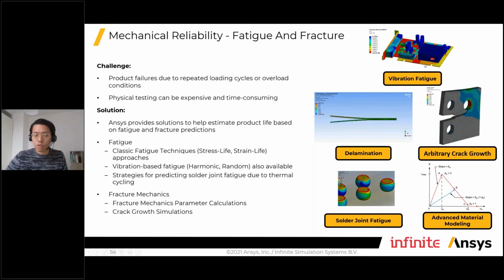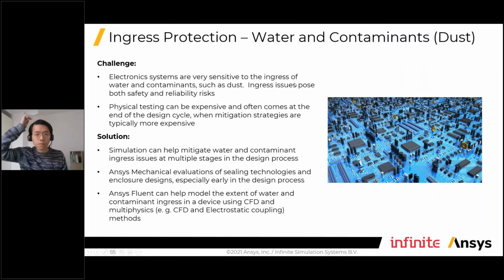You see the vibration fatigue, which part is going to have a lower lifetime, and then start thinking about maybe different mounting strategies, maybe a different arrangement of your components to improve your lifetime. Water and contaminations, you want to conform with different IP standards, 65, 67, even 69, and you are going to do this kind of analysis to make sure that they conform with the standard before you send it to the test labs.